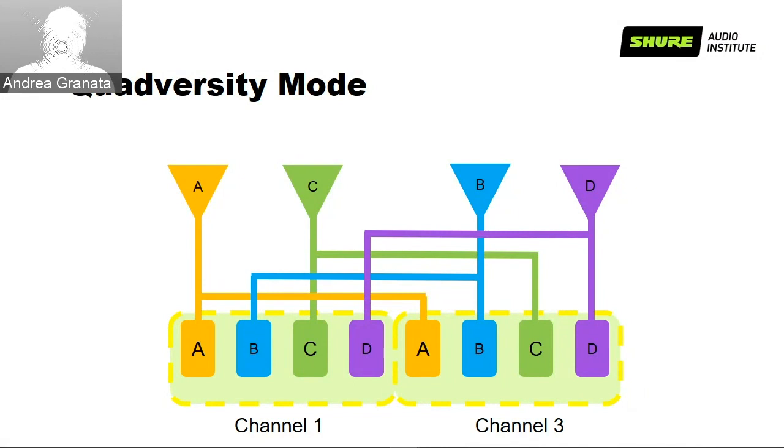In this way, I can cover 2 areas, but I sum up the noise from outside with the noise from inside. And in a modern environment, this can be extremely challenging. Therefore, quad diversity is another weapon that you can use to fight against RF noise and lack of coverage, or the need for extreme coverage, and the applications are countless.